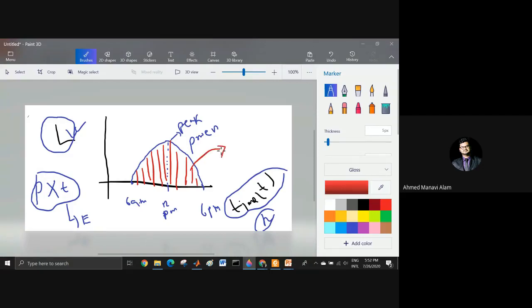That area underneath is my H. You remember the unit of insolation? It is kilowatt per meter square. Now you are getting the area, which is noted as H, multiplied by hour. What will be the unit of H? Can anyone tell me?